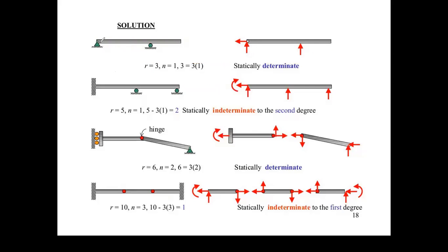Say this is one of the beams, right? First of all, we have to see the R. What is the total number of R? They are saying R is 3. How is R 3? This is a pin support. That means it can rotate clockwise or anti-clockwise. It is restricted in the horizontal direction and in the vertical direction. So that means two unknown forces are here.